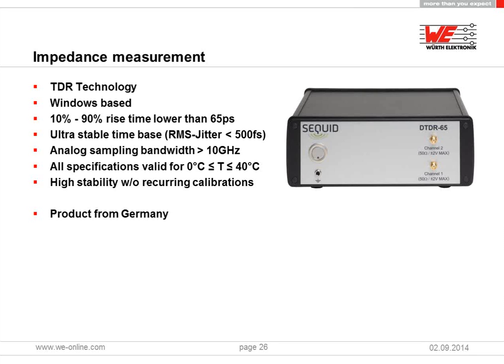We learned that we now have an integrative calculation and documentation which helps you also for your project documentation, avoiding some risks. We have learned that now we have the ability of the calculation of hedged reference layers, which is also important for you, as we have learned. And we have seen that the design and measurement of specific flex rigid impedance test coupons with reduced area is possible.